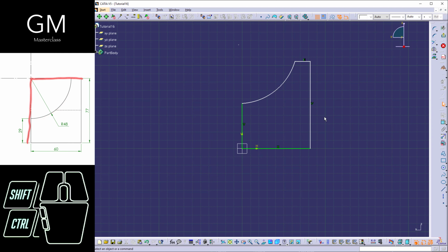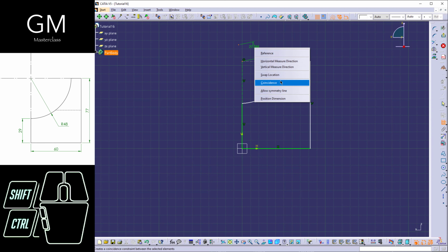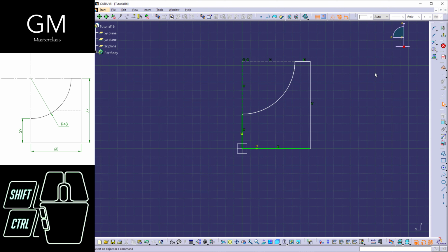This matches with these axis lines. So I'm gonna create a line right here that is meant to be a construction line. So right here I'm going to click on these two and I'm going to select this option, the construction standard element. Then I'm going to say that these lines, this point and this point, is going to be coincidence, right? Everything looks good. Then I'm going to create the dimensions for me to define it.